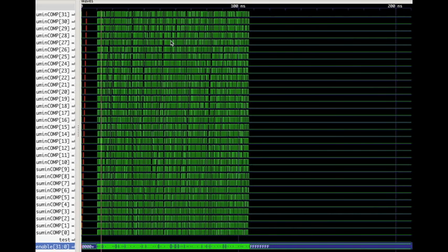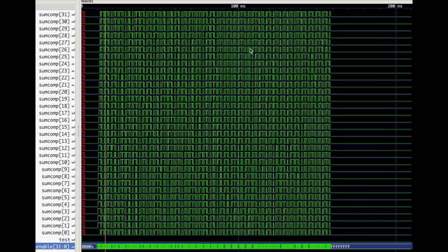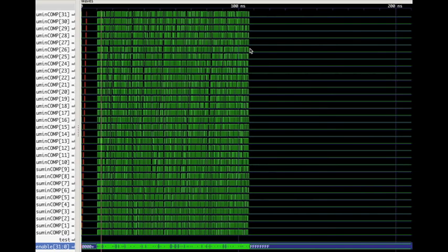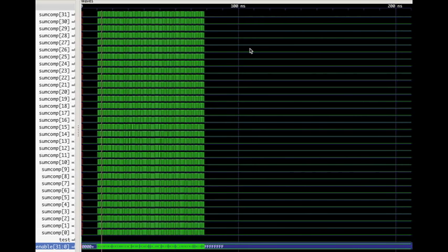And the last simulation is the ragged wavefront flow presented to the shifter. And the ragged wavefront flow was generated by an adder with variable carry chains. And you can see that it runs quite a bit faster than the 2D pipeline version, but not quite as fast as the ones that didn't have the ragged wavefront flows or the 2D pipeline flows.